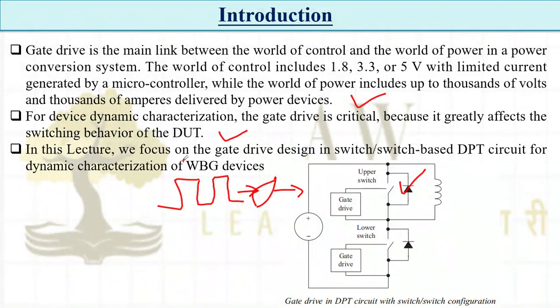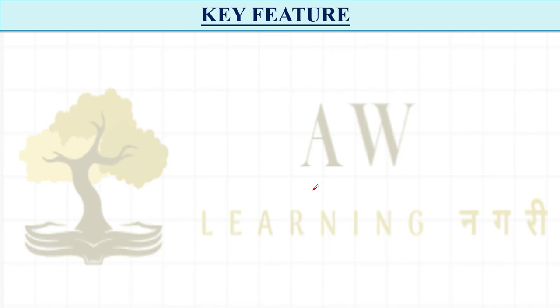In this lecture we are focusing on the gate drive design in a switch-based DPT circuit for dynamic characterization of wide band gap devices. We will learn how to design the gate driver, what the different components required in a gate drive are, and what combination is included in the gate drive. Everything we will see. So what are the key features of the gate drive?